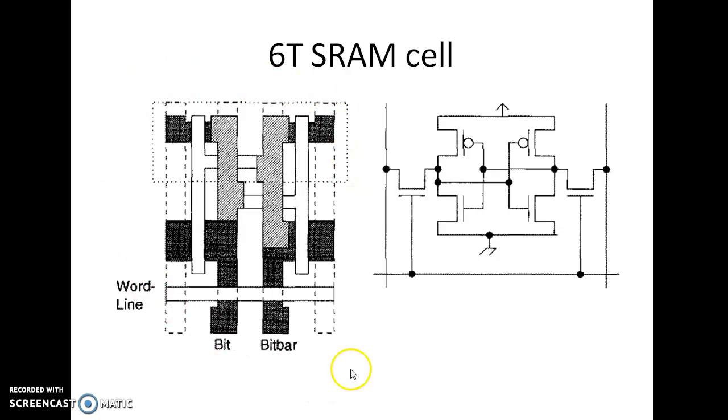And the layout, you can draw in any fashion. This is one of the possible combinations of layout, which is on a double silicon pattern. Right? And you can easily conclude what the advantages of 6T SRAM cells are when compared to 4T. The advantages are less power dissipation, easy to fabricate, and fabricated in less area because there are no resistors.